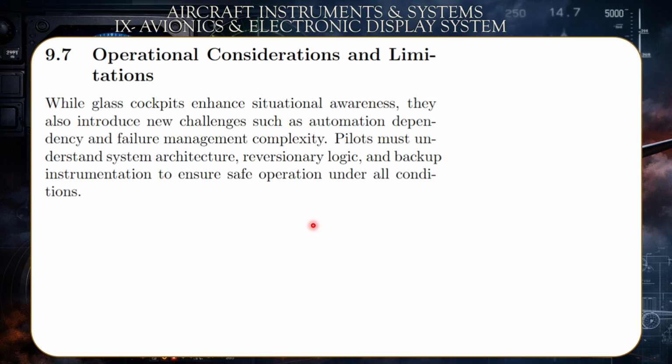Why? Because the computer systems would rely on these measurement data in order to automatically fly the aircraft. In case these measurements, and one or more of the sensors, are faulty, the autopilot would be operating on false premises, which can bring down the entire aircraft or cause dangerous maneuvers to take place. So that's why the pilot should understand when to disconnect the autopilot in case you have an emergency as such or an incorrect sensor reading.